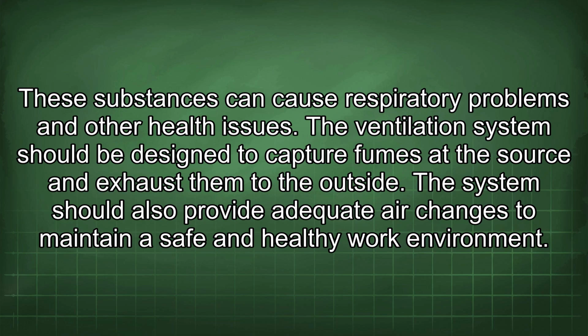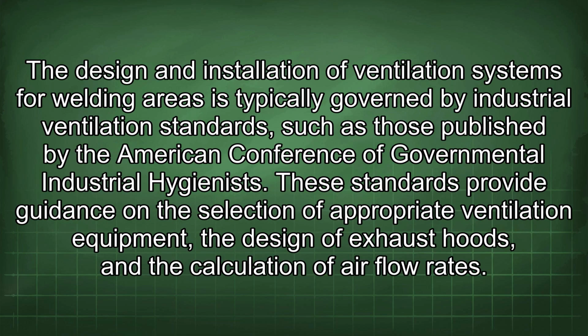The ventilation system should be designed to capture fumes at the source and exhaust them to the outside. The system should also provide adequate air changes to maintain a safe and healthy work environment. The design and installation of ventilation systems for welding areas is typically governed by industrial ventilation standards such as those published by the American Conference of Governmental Industrial Hygienists. These standards provide guidance on the selection of appropriate ventilation equipment, the design of exhaust hoods, and the calculation of airflow rates.